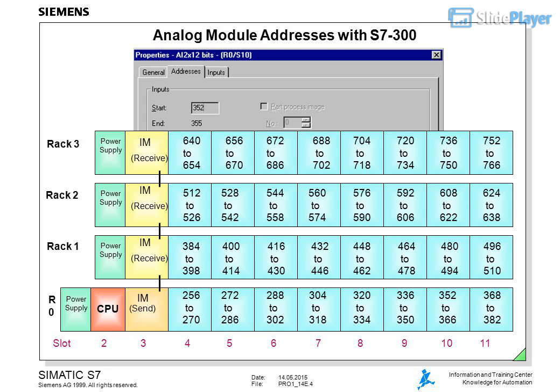The S7300 has a special address area for analog inputs and outputs, which is separate from the process image input and output tables for the digital modules, PII/PIQ. This address area extends from byte 256 to byte 767. Each analog channel occupies 2 bytes.